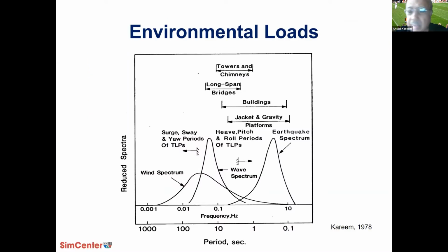So, back to our structural dynamics expertise, we look at what the loads caused by wind are. As you can see from this particular sketch, we have a spectrum, which shows the bandwidth of energy over frequencies in earthquakes, wind, and waves. More flexible structures would be more sensitive to wind, and stiffer structures would be more sensitive to earthquake. The difference is how we transform earthquake ground motion to the structure, and how the wind fluctuation is transformed to a load. That is a little bit more complicated because there is no one-to-one transformation, and that's where things become more complicated.